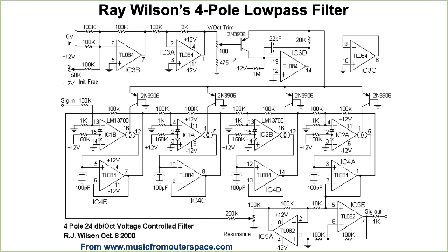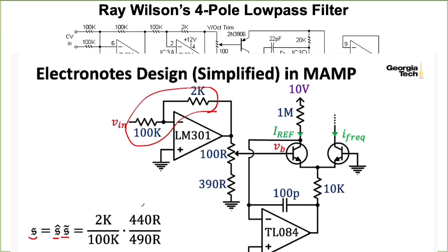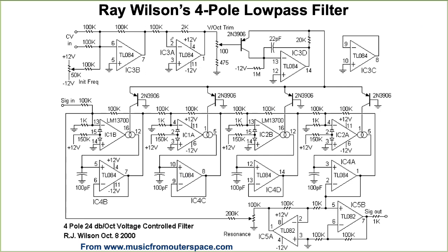The input structure is also similar. Just as the Polyfusion folks needed 2 op amps, where in the case of creating a current sink with an exponential voltage to current characteristic using NPN transistors, we only need 1 of these. Here we need 2. We're mixing a couple of external control voltage inputs provided via jacks with a setting set by the user via front panel knob.